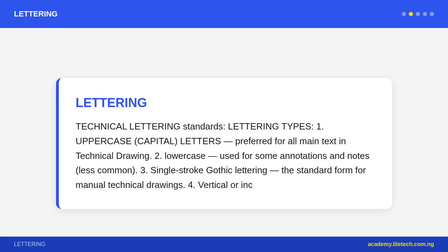Dimensioning tells the manufacturer the exact sizes and positions of features. The 3 elements of a dimension. 1. Dimension line, a thin line with arrowheads at both ends, running parallel to the dimension being measured. 2. Extension lines, projection lines, thin lines projecting from the feature to beyond the dimension line. They do not touch the object outline.